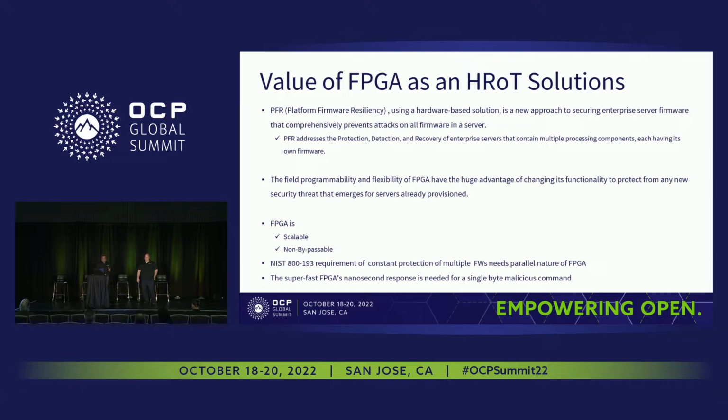So PFR is an Intel term, but it came from NIST compliance 800-193. NIST doesn't say exactly how to implement that, but PFR is basically Intel's implementation of it. PFR uses a hardware-based root of trust. It's a new approach, because it addresses these three big things: protection, detection, and recovery.